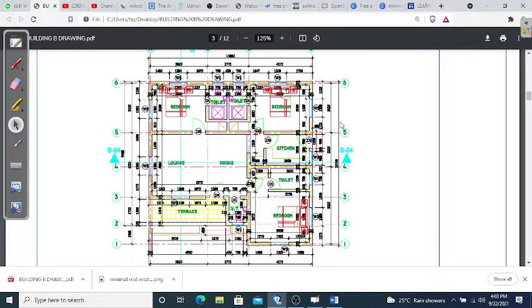And what the unit you have on that item list tells you is in what quantity you are measuring. Are you measuring in cubic meters? Are you measuring in terms of volume? Are you measuring in terms of linear meters? Or are you measuring in terms of area? So that is what will guide you. To every activity you find on that list, the unit of measurement is quoted against it, so that it serves as a guide for anyone who wants to do an estimate. So when you are estimating for that particular item, you will know that, okay, I'm estimating it in terms of area or I'm estimating it in terms of volume.